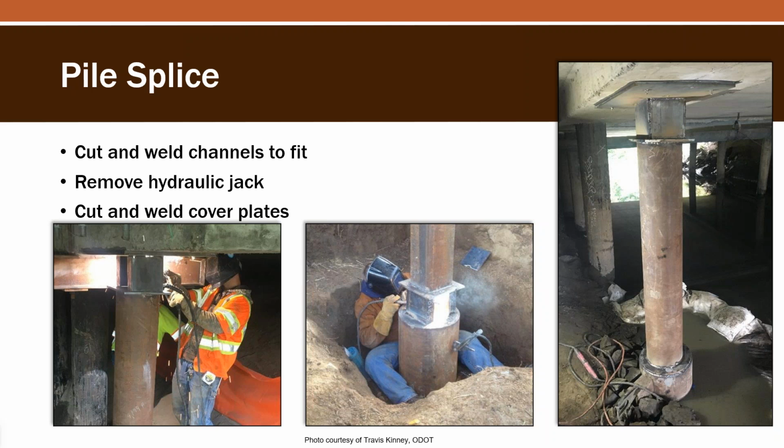The example in the middle there, you can see they're doing that splice down at the bottom of the repair, and then on the left-hand side, and then I think that's the completed section on the right, they're making that last splice up at the top. I see a huge steel plate on the repair on the right where it interfaces with the concrete deck or a concrete slab above it, and that's just because the original timber stuck all the way up through it, and so they would have cut it off flush with the concrete to make that happen.